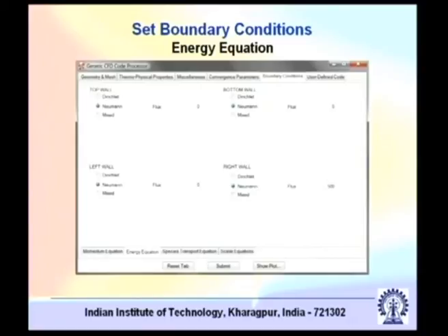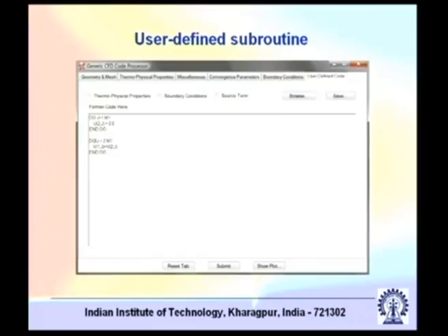At time equal to 0 you have a particular value of temperature and that is a unique value, it is not an artificial iteration driven value. In an iterative solution, even for a steady state problem, you could start with an initial guess, but that is an artificial initialization. Here you have a real initialization where at time equal to 0 you have a particular value of temperature. Based on that it will subsequently evolve and it will not create any problem for having a Neumann boundary condition at all the boundaries. So do not confuse those examples with this particular example that we are considering.